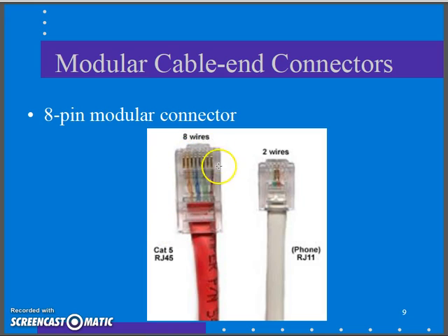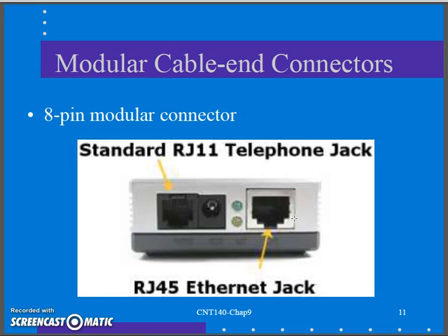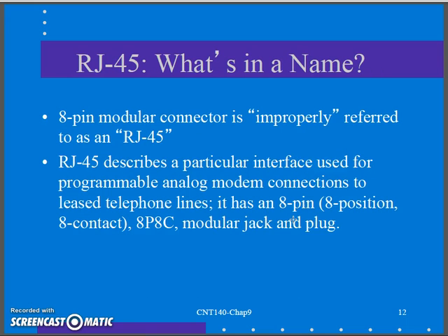Again, here's another reminder of your modular 8-pin connector, RJ45, versus our 4-pin modular connector, what we would call the RJ11 that we would use for phone. Make sure you can see and recognize the difference. Here's looking at it from the front, RJ45 versus RJ11, modular 8-pin versus modular 4-pin. And then there's your RJ11 jack and RJ45 jack, just comparing the difference.